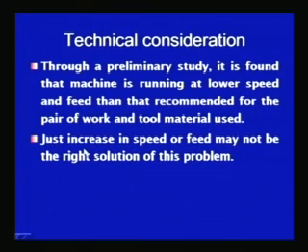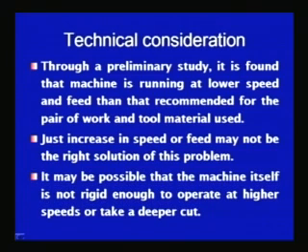So, if the work study man thinks that simply by increasing the speed and feed of the machine the production rate can be increased, then it may be incorrect and wrong in many cases, because simply increasing the speed and feed can lead to poor quality of the product or increased tooling cost, because an increase in feed and speed may lead to failure of the tools, or the machine itself may not be able to withstand those high speed and feed conditions.